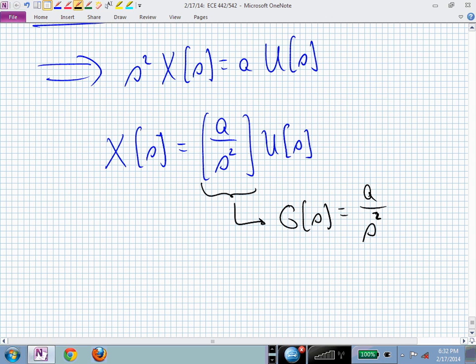This now has two poles at the origin. Is that very easy to stabilize? It's right on the stability boundary, isn't it? And if you simply fed output feedback around that, if this was the classical controls class, you would just increase the frequency of oscillation, but you wouldn't stabilize those at all. Those two poles wouldn't move into the left half plane. So you would just make a faster and faster oscillator as you cranked up the gain K. Maybe not a good thing.